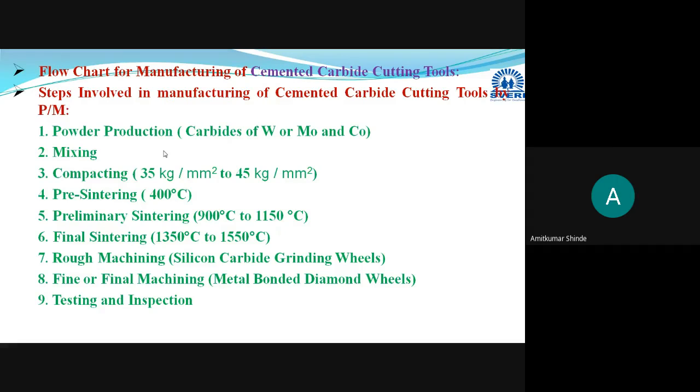Okay, and here in the mixing you have to add these lubricants, and you have to try to get the uniform and homogeneous mixture with the help of different instruments like different mixers, different blenders. You can use Y-cone blender or double cone blenders, which are most commonly used for this process. And after that, that uniform and homogeneous mixture obtained is subjected to the compacting or pressing stage.